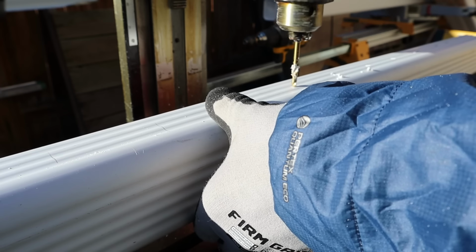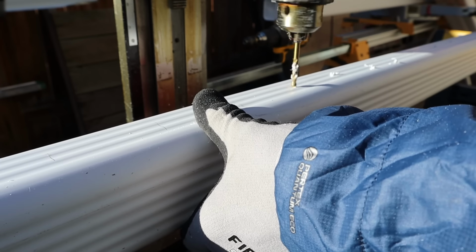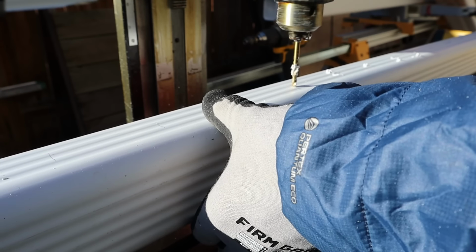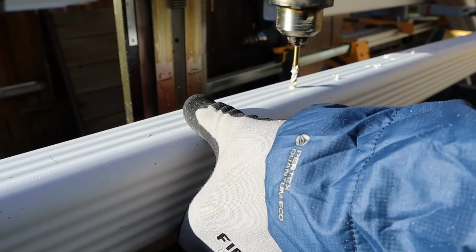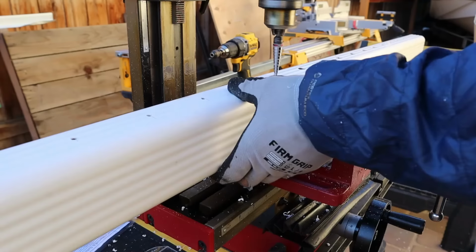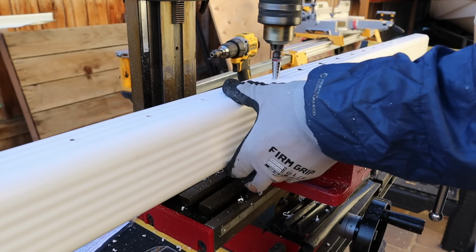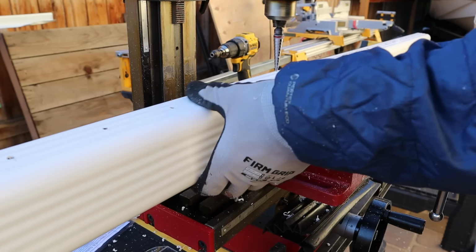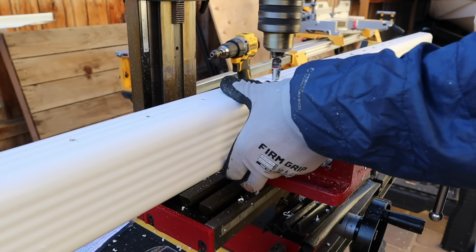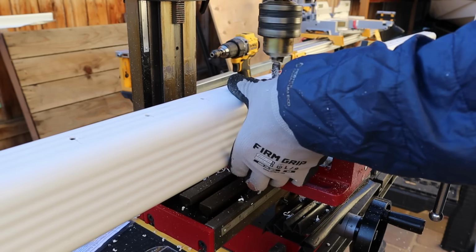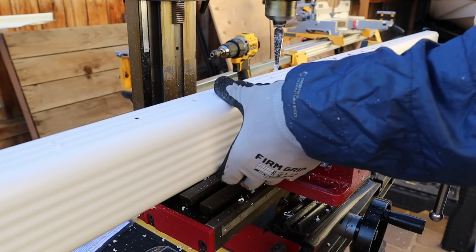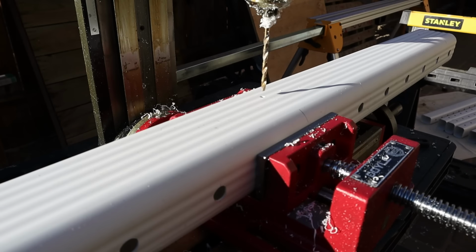Now I started by doing a pilot hole. So I just used a small bit and did a pilot hole on every one of those marks. And I already had my drill press set so that those holes were perfectly on center. And then I went back with my step bit, going to the exact depth I needed to achieve that 15/32 hole size, and making sure that those are all done clean. A step bit works really well for this.